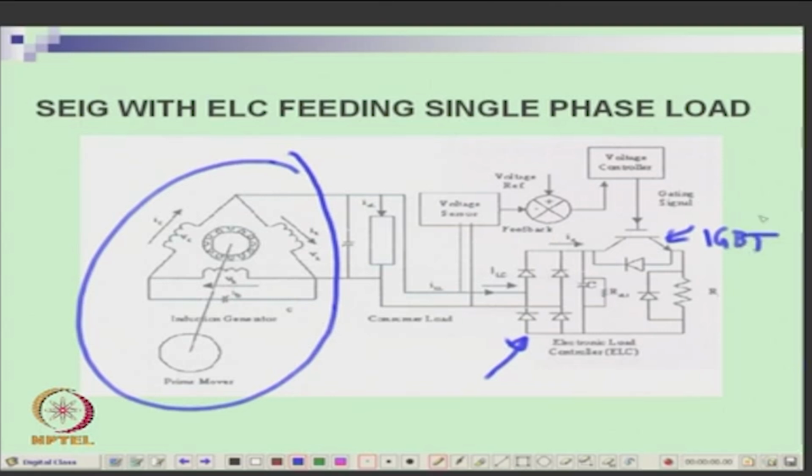Till now a lot of work has taken place, we have proven it works and it works in the lab. A few things have been put to the field, but we are not 100% satisfied, because in some conditions the IGBT will burn. So, you have to develop a reliable controller, so that it is robust, the IGBT is safe and a good protection is given. That is again the problem in hand.